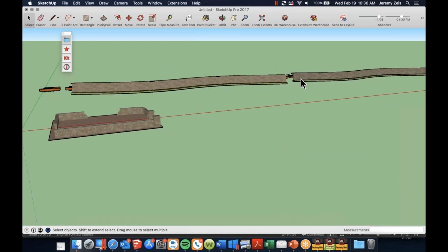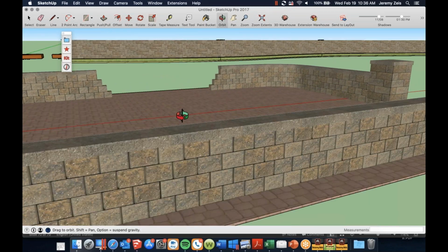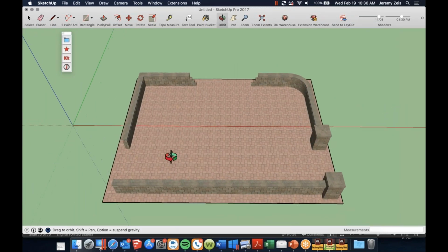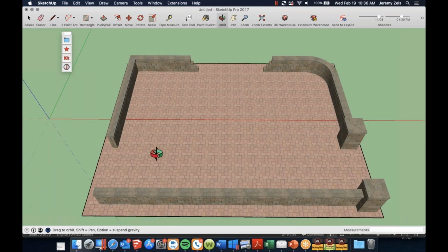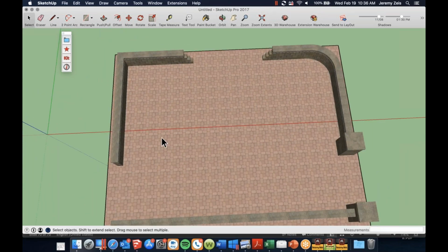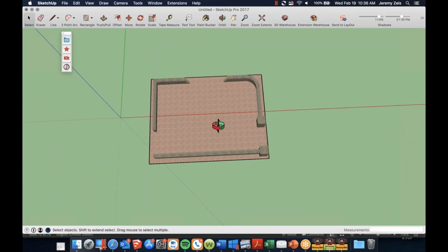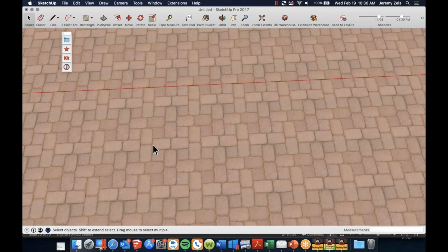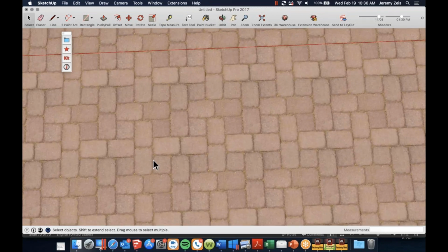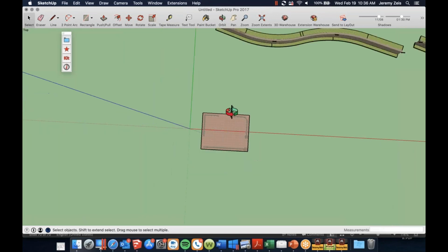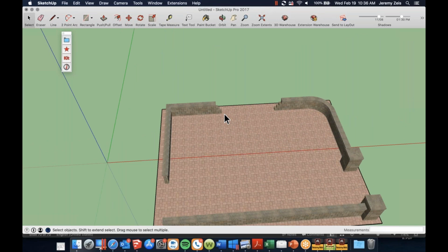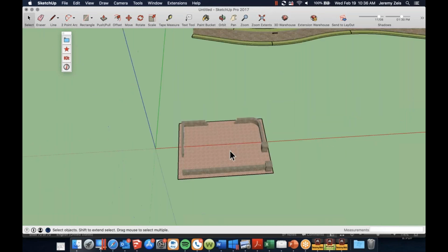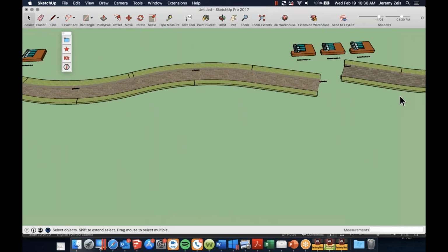Now, again, in just a few seconds, we've brought in our Courtyard that I designed a while ago. I did a step down at the top opening, some posts on the right-hand opening, and just a split end on the left-hand side. But again, you can see we've put in a default paver here, but you can always texture it with your own type of paver that you want to do. But really, you could see how fast we brought in a 3D model from those Ruby scripts.